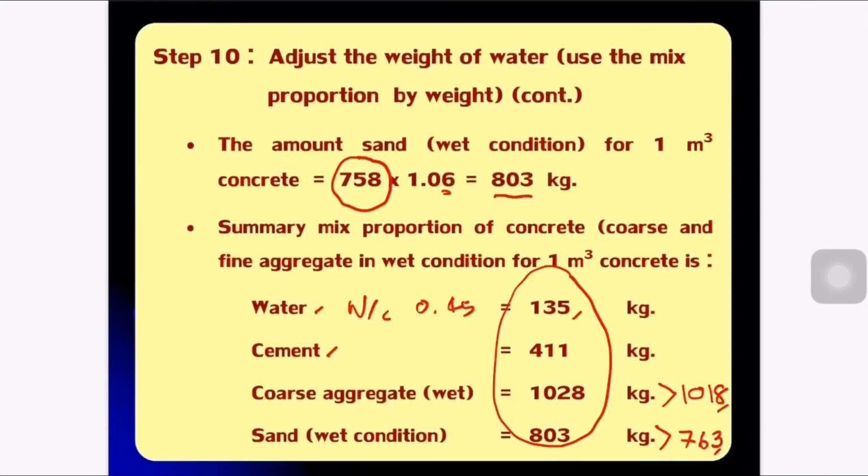If the slump of concrete meets the requirement 25 to 50 millimeters, place the concrete into the standard cylindrical mold having 15 centimeters in diameter and 30 centimeters in height, in order to check the compressive strength of concrete at 28 days. If the slump of concrete and the compressive strength at 28 days meet the two requirements, it is suggested that this mix proportion is ready to use.